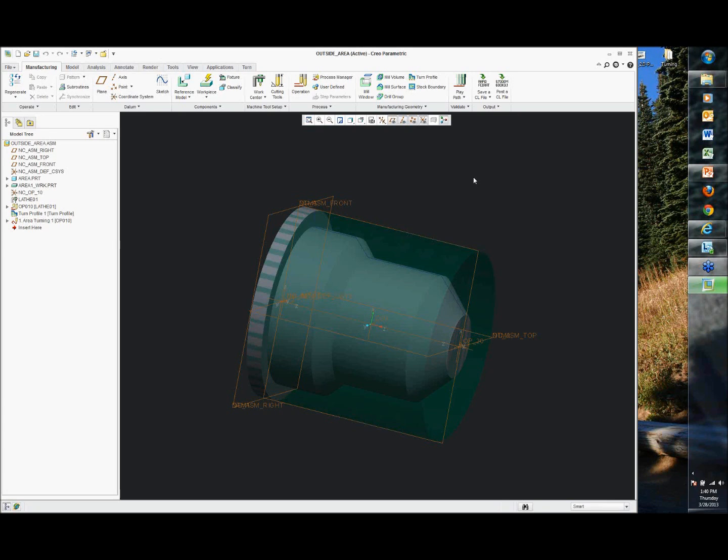Well, what happens, this is more in milling than in turning, but in milling, if you create a pocket and you're using a 1-inch end mill with a 1/2-inch radius on it, but your pocket only has 1/4-inch corners, there's still a 1/4-inch left in those corners. Well, that material removal, until you go in there and figure out what is actually left, and you have to calculate it and tell it for the material removal, it doesn't do it.